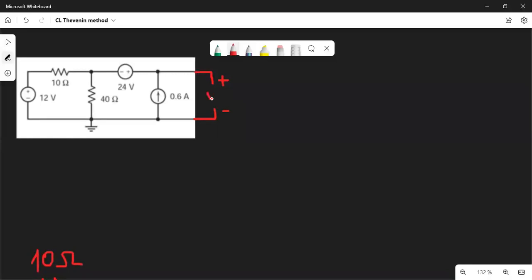And between them, there is some kind of voltage source. We should find this exactly. Let's call it VO. So if it's VO, what is the potential here? Now we want to use the node voltage method to find the other values here. As you saw in the picture, we take this node as a reference node, which means its potential is equal to 0. Electric potential is equal.